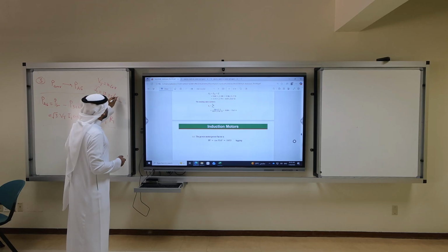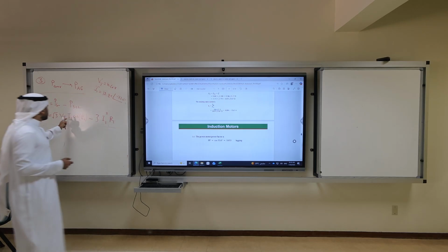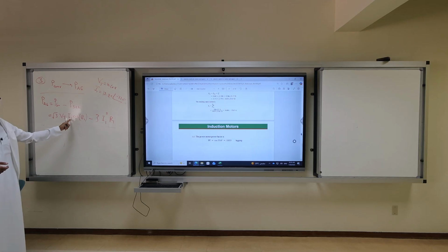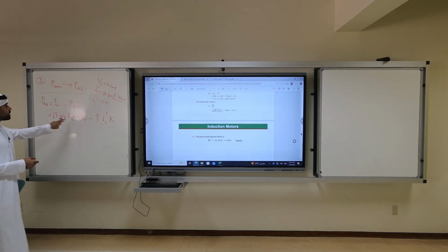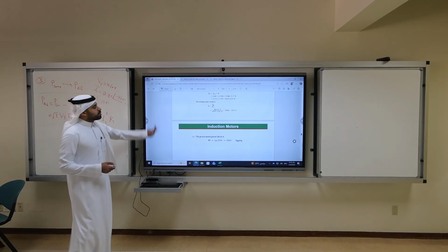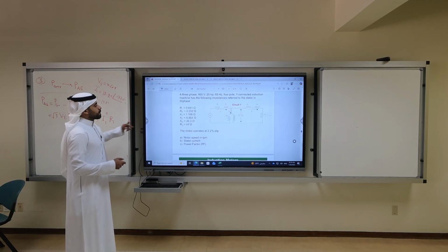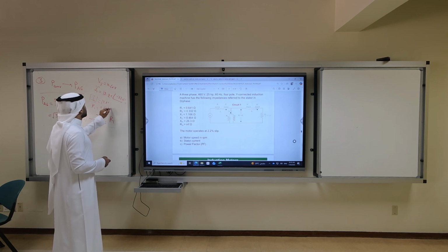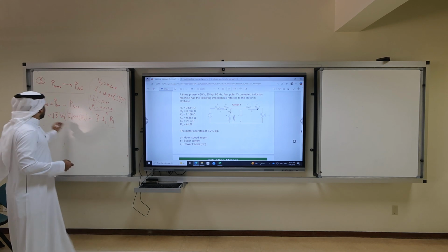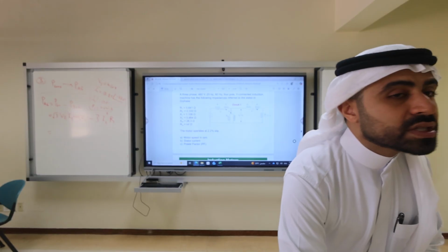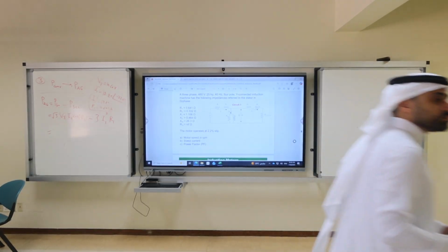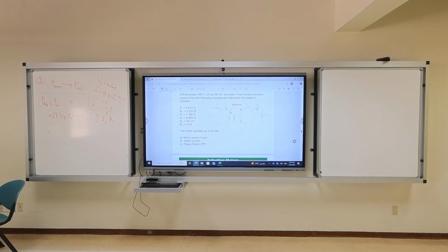18.88 angle minus 33.6. Now in this equation, do you put magnitude or angle? Only magnitude. So what is the I1 magnitude? 18.88. So I have these numbers. What is R1? 0.641. So do the calculations. What is the P air gap? Who doesn't have a calculator? 10300. Okay, what is the input power?